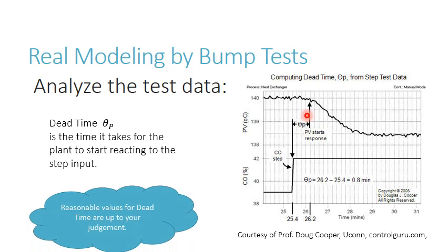Now, that's really up to your judgment. You might say the dead time ended here because you see it going down just slightly. You might say it ended here because you see it going down slightly here. That's really up to you. It's a matter of judgment.